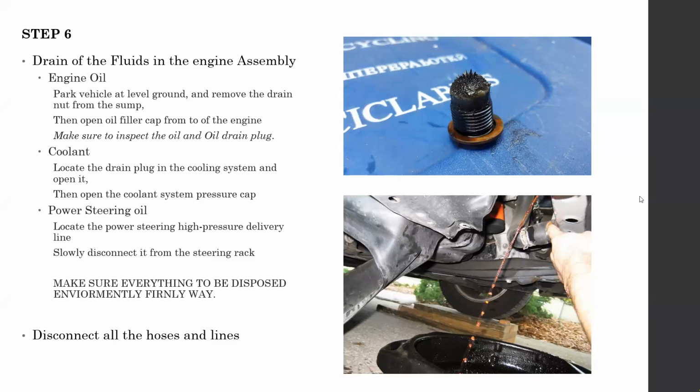If that color is there, definitely you have to look inside the engine, as something is going very wrong. Once you see it, if you are not going to do something, there's a possibility of engine seize-up or something breaking off. So before that, the best thing is to dismantle the engine and see.